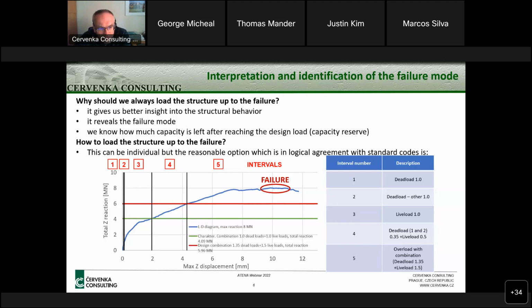In this case, if it is at a single point, it is maybe advisable to apply displacements because the analysis is then more stable and easy to calculate. But of course, if we are considering a real design situation, it's not possible to change the loading to displacement control. If we have body forces, some earth pressures or pressures on the surface, it is not possible to change it to a displacement type of loading. So we need to load by forces. And then, of course, it's a question, how can we go to post-peak if we are loading by forces?